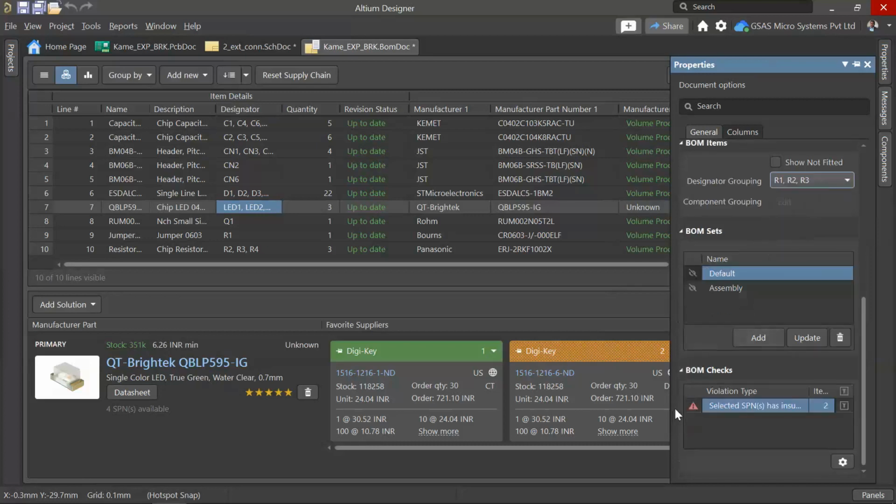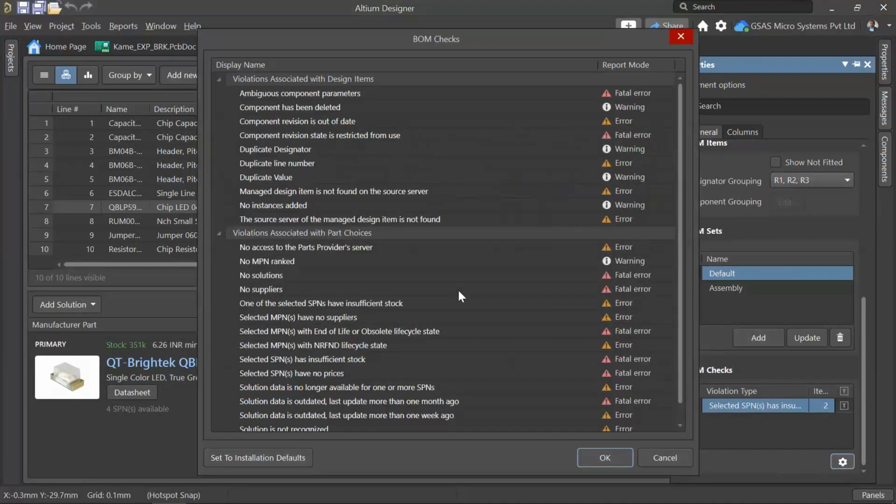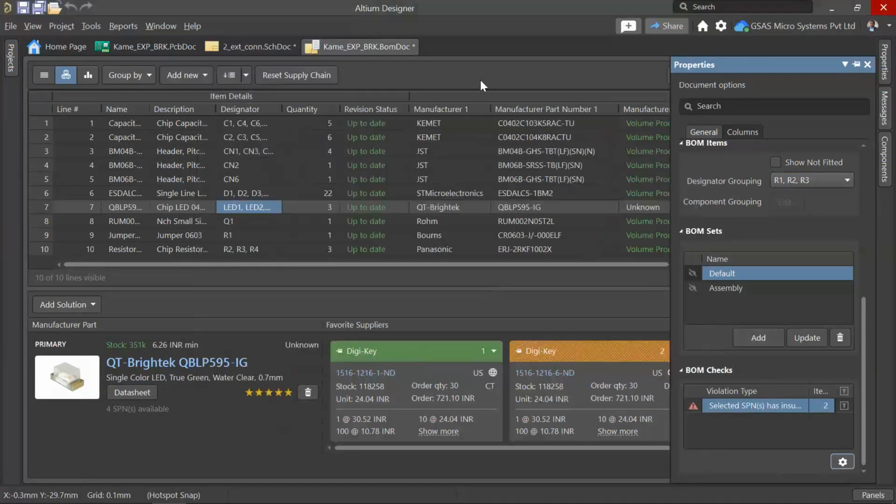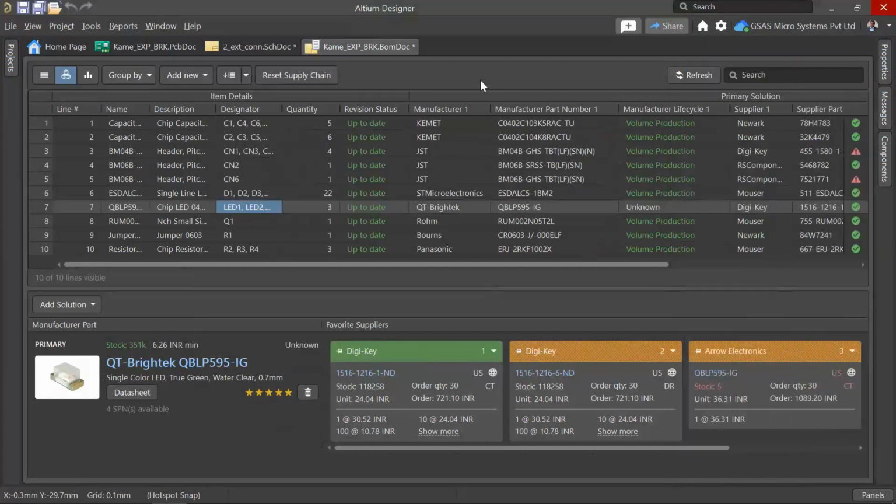I discussed what all issues we have here and how we can manage them from here. How you can manage the components by using the ActiveBOM, and cross verify your components' availability at any point of time during the design phase. And once your checks are done, now we are good to generate the bill of material. The same, go to reports, bill of material.